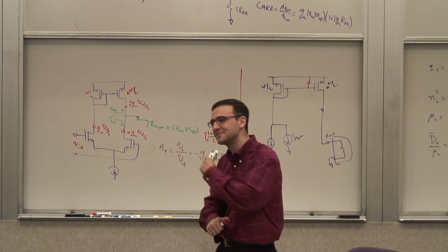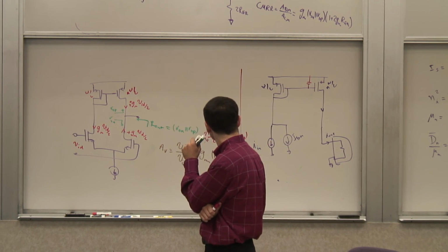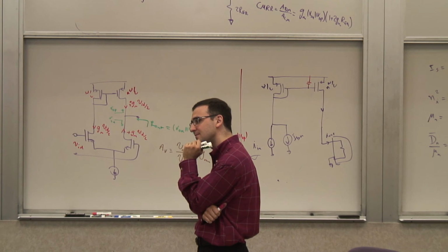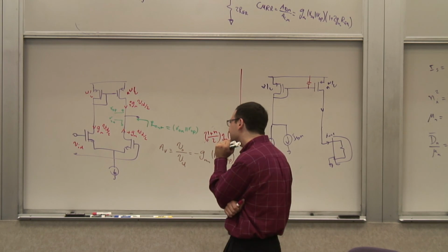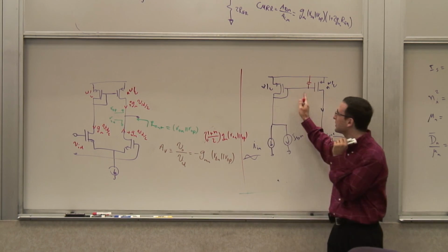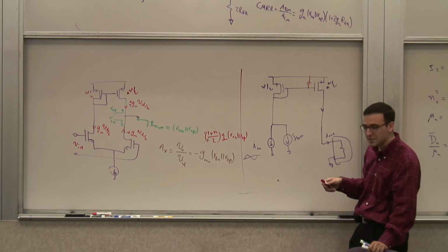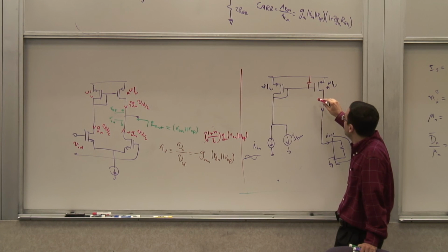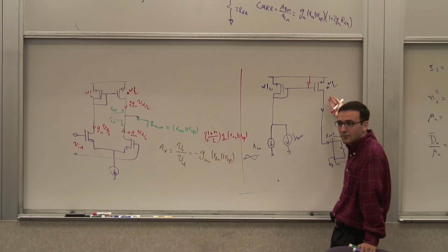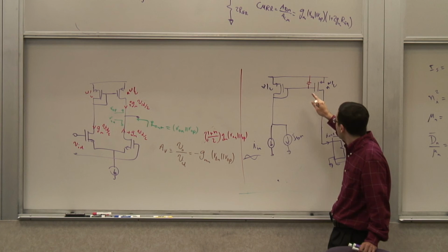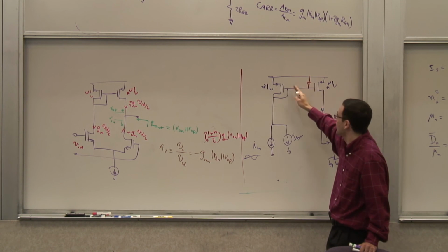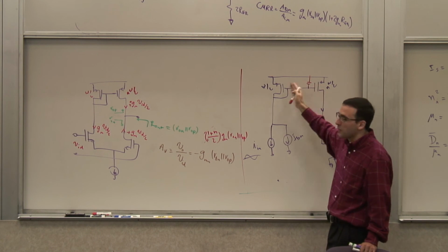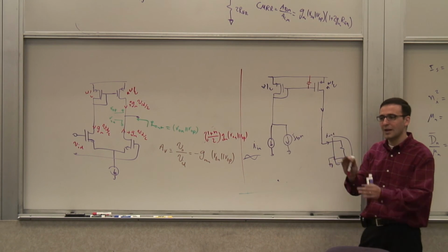Quick question. Yeah, sure. So does that mean people do adjust the size of the transistor in that respect to some extent then? Or do they just not do that at all? Right. Well, this is not a very good current amplifier in general. You will see better ones next quarter when we talk about the frequency response. But you can use it as some basic current amplifier. But as you pointed out, there will be some limit to how much gain you can get when you go through this. You don't want to get a ratio of 1 million, for instance, right?